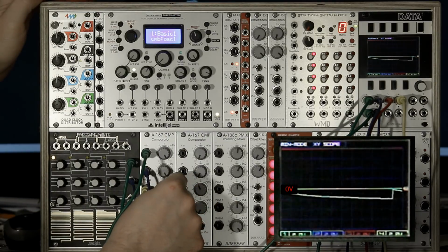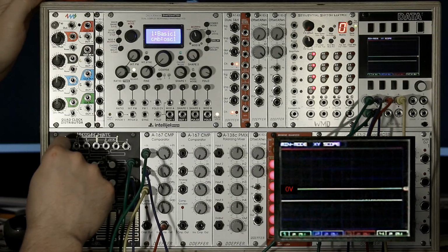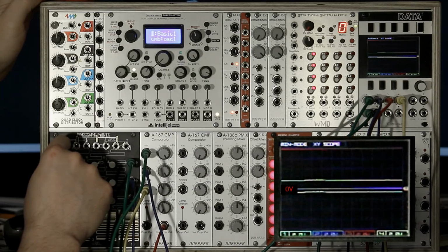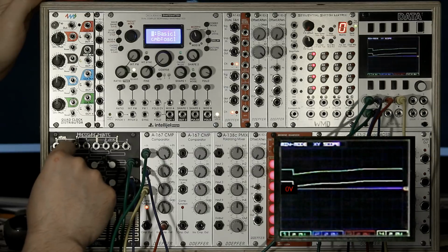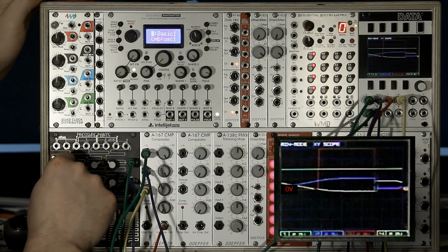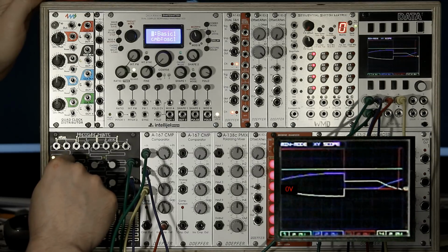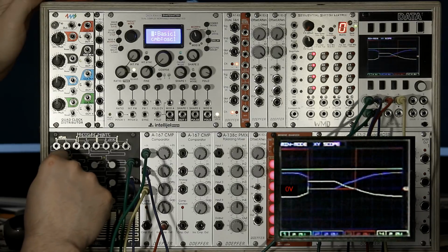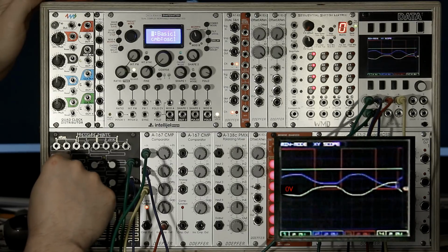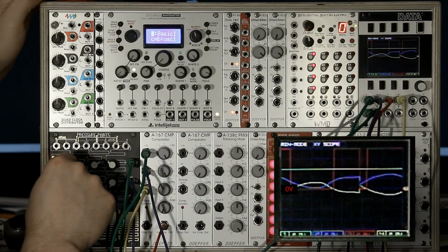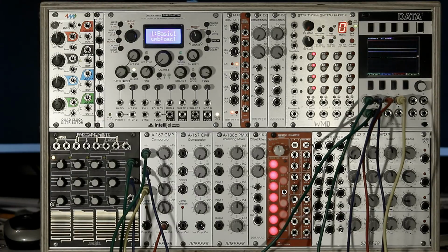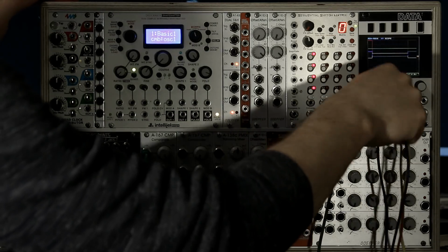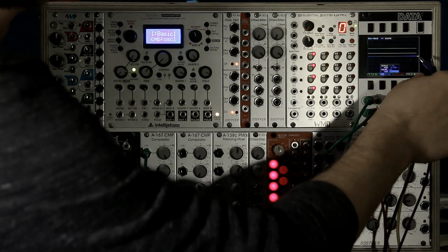If we move the offset value to some negative voltage, you will notice that the state changes, even though the second blue voltage didn't become larger than the green one. To avoid confusion, it is very important to understand this if you are using an offset. It is better to say that this comparator unit changes its state when the analog sum crosses 0.